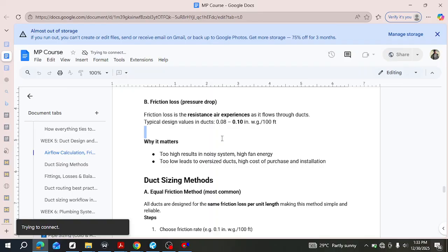So around the two edges, the up and down, you will have to go the extra mile to seal it up, and it's still not going to be as airtight as it should be. That is one of the disadvantages of selecting circular ducts, but still, it is a good option.